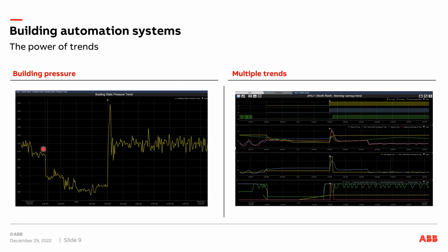I can look at building pressure. This was an important one for our building in particular because we had issues where the building pressure had gotten too high, and then it created a security issue because your doors weren't shutting and latching because there was too much pressure. But at the same time, we wanted a higher pressure because as you got semi trucks that are backing up and either loading or offloading our products, either bringing parts in or shipping drives out, we don't want all those fumes from the exhaust from the diesel trucks coming into the production area. So we want high building pressure to keep the air going out instead of coming in.